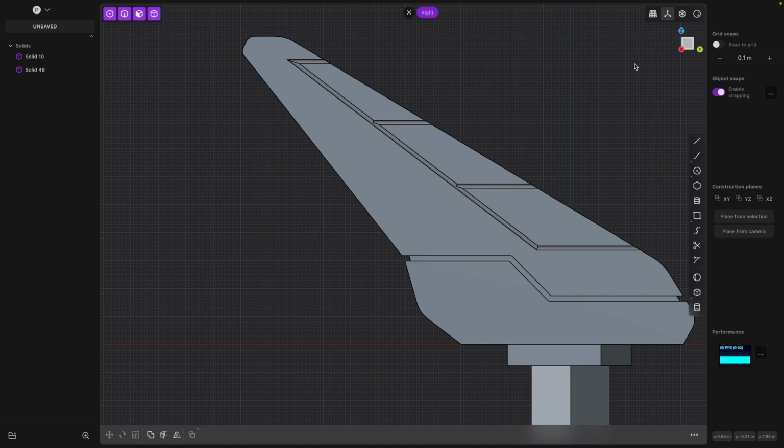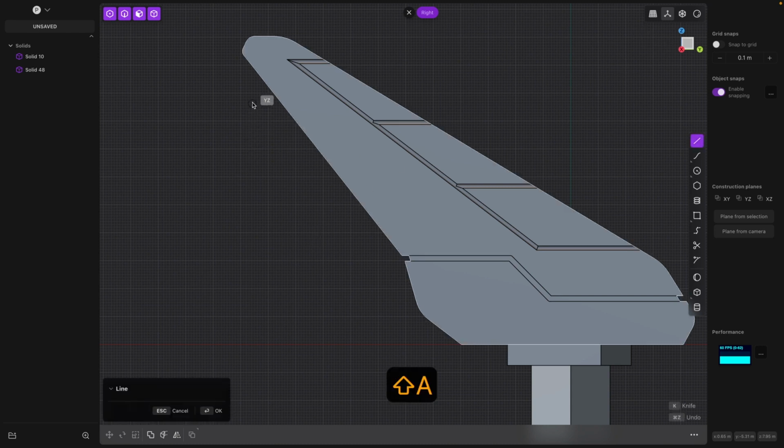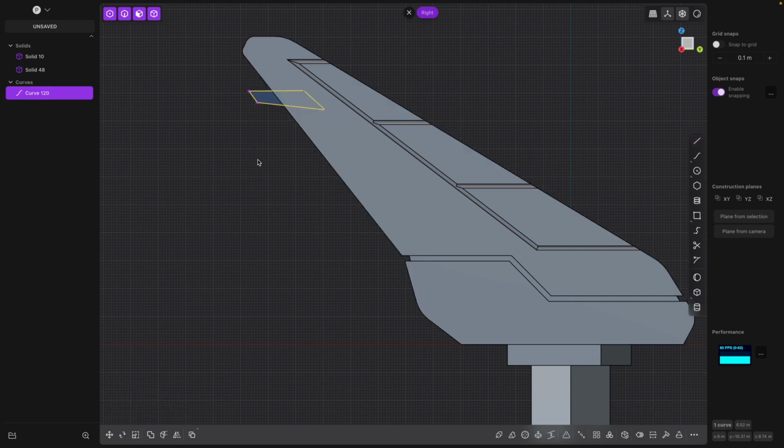So yeah, let's go add one more kind of a raised detail just to give you one more example. So we'll create an object that looks kind of like this. We'll draw a thing this way. We'll come down. I'm going to hit Alt-Z so we can see through this because we were out of X-ray mode. I want to come down to maybe about there, come up at an angle. Yeah, that'll look nice, and then close this off. So we have a shape like that. I'm going to hit B for bevel and drag this little thing to give us some little curved edges on this shape.